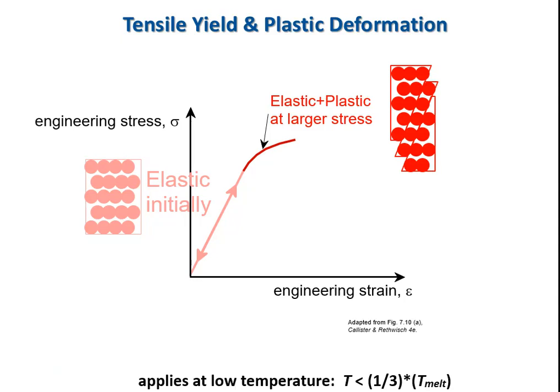That's a good benchmark number to think about, because if we go over that, we start to get viscoelastic behavior even in metals. Polymers will display viscoelastic behavior even at room temperature sometimes, which might be a significant fraction of their melting point. But if we're looking at a metal, generally if we're at 1/3 of the melting temperature or less, this is the type of behavior we see. And for most ordinary structural applications, we're working on or around room temperature, so that's just fine.